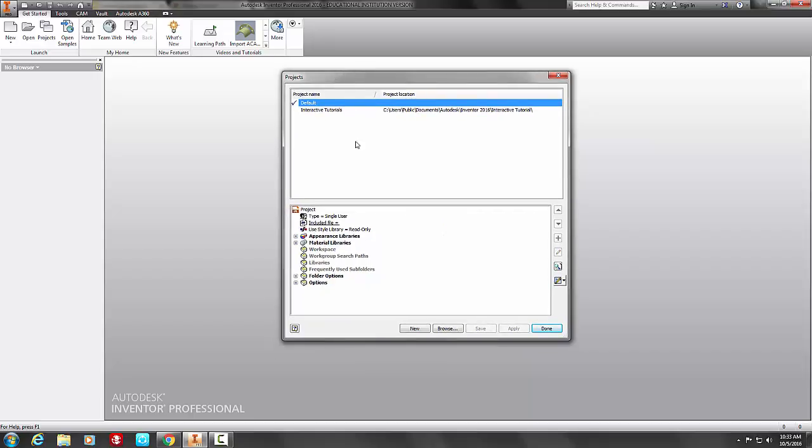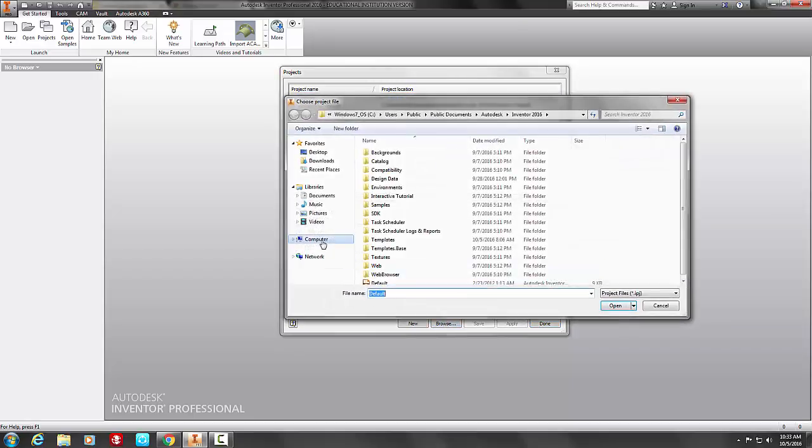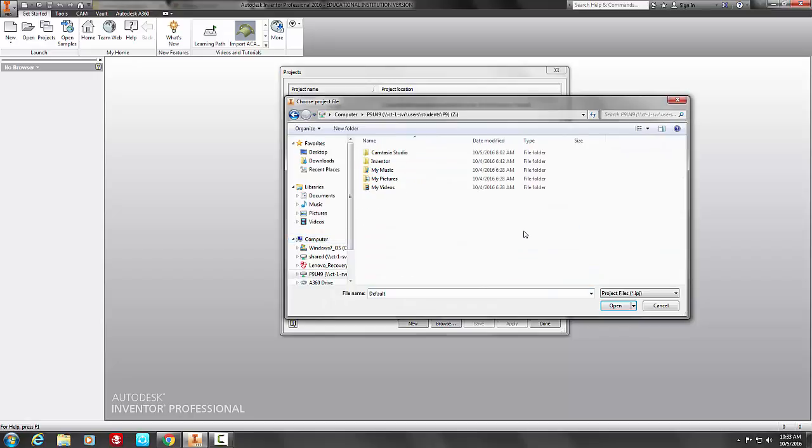You'll recall in the previous video that I already set up the Inventor project, but where is it? Well, when you log off, the computer will change. Inventor will no longer look at your profile. So what you need to do, it's very easy. You're going to browse to that Inventor project file that I referred to earlier. It may have been unclear what that project file was for, but now we're going to find out why. So I'm going to browse, go to Computer, go to my Z drive, Inventor folder. There's my Lego project folder. And now I'm going to select that Inventor project file, IPJ.